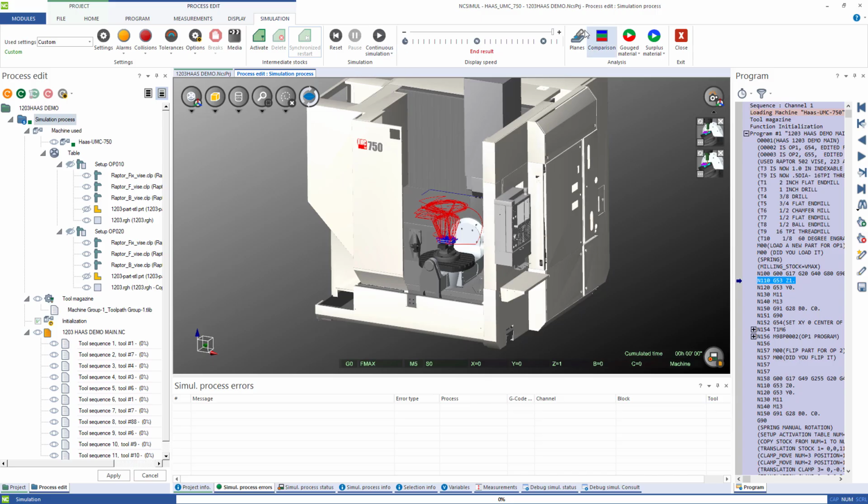And at the end of that, you run this comparison tool. And again, that's comparing the original part model to what we just cut in the G code. Your red is your gouge, your blue is your excess, and your green is hitting your specified tolerance, which we can set job by job or for your overall environment if everything was standardized.